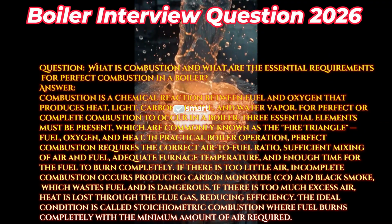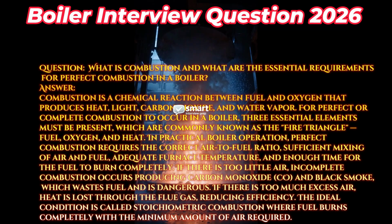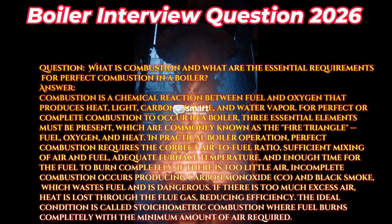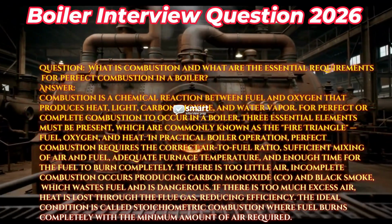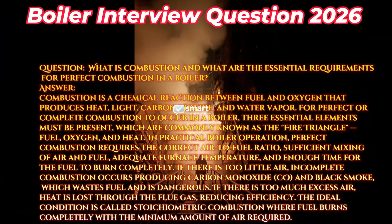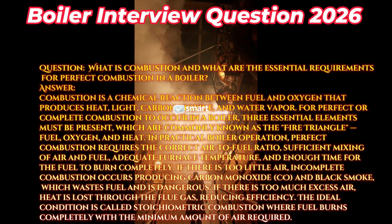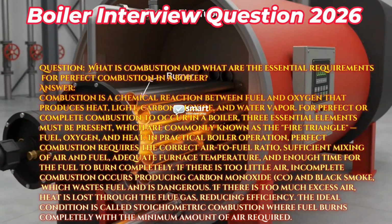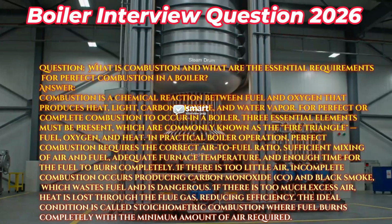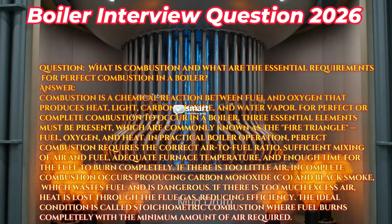In practical boiler operation, perfect combustion requires the correct air-to-fuel ratio, sufficient mixing of air and fuel, adequate furnace temperature, and enough time for the fuel to burn completely. If there is too little air, incomplete combustion occurs, producing carbon monoxide, CO, and black smoke, which wastes fuel and is dangerous. If there is too much excess air, heat is lost through the flue gas, reducing efficiency. The ideal condition is called stoichiometric combustion, where fuel burns completely with the minimum amount of air required.